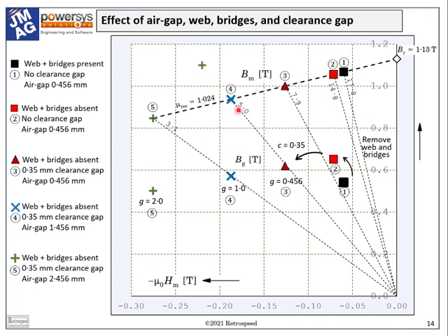Remember that the worst case demagnetization is under load conditions, and maybe under fault conditions, and maybe at an elevated temperature. So there has to be a safety margin in the open circuit operating point at room temperature, which is what we have here. It's not a hard and fast rule, because in the complete design process it's necessary to simulate and calculate all the worst case conditions and then to test them in the test lab.